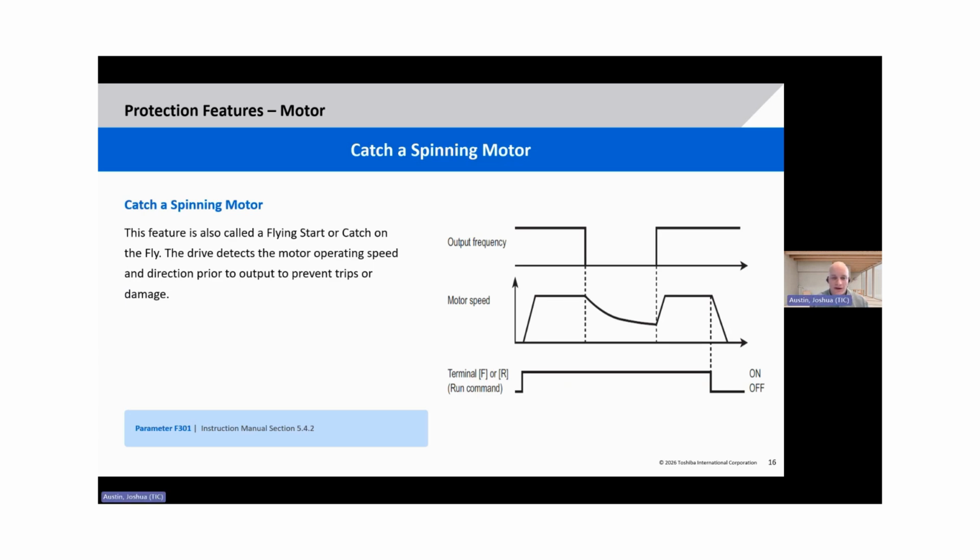So this is where I got a little bit ahead of myself on the last slide. Catching a spinning motor, or sometimes called a flying start or catch on the fly. This happens in multiple scenarios, actually. It could be because the drive faulted and the motor is coasting to a stop. It could be because the VFD lost power and the motor is coasting to a stop. Or it could just be that there is an outside factor that's causing the motor to rotate prior to the